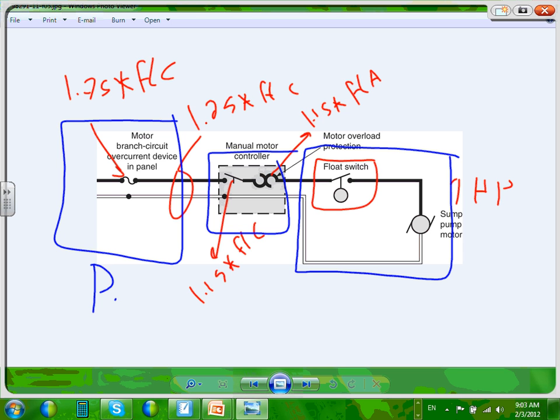So for this exercise, the motor controller fuse is protecting the conductor, correct? The fuse is protecting the conductor, is protecting the controller, and is protecting the pump. I'm just looking at the OCPD. Yep, the current capacity in the conductor, the fuse is protected. Yes.